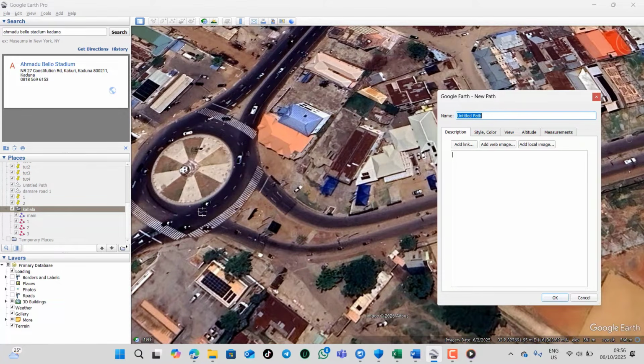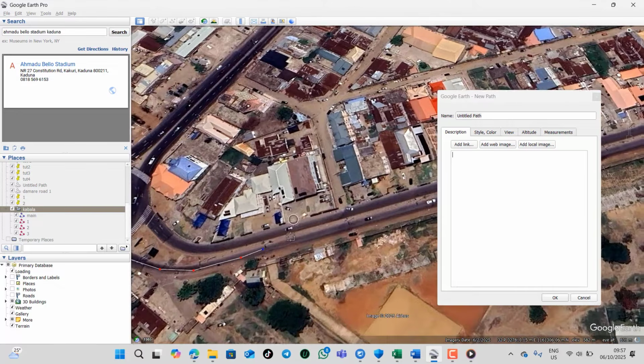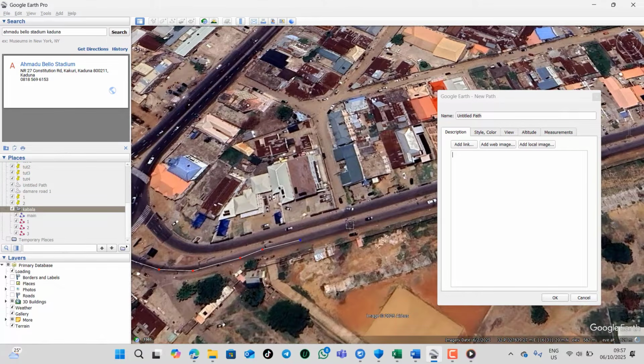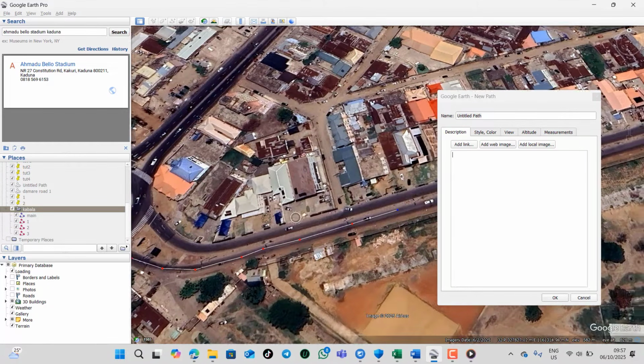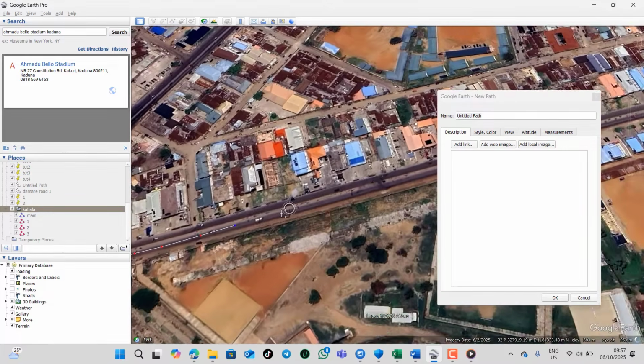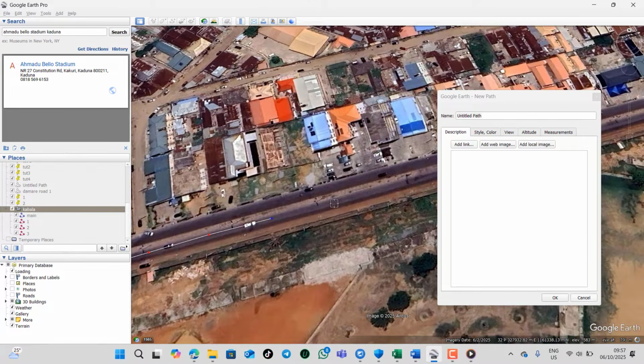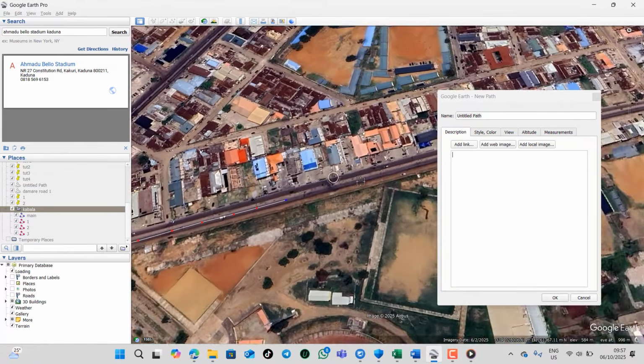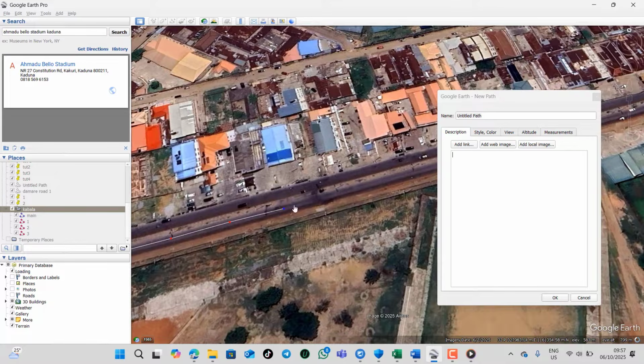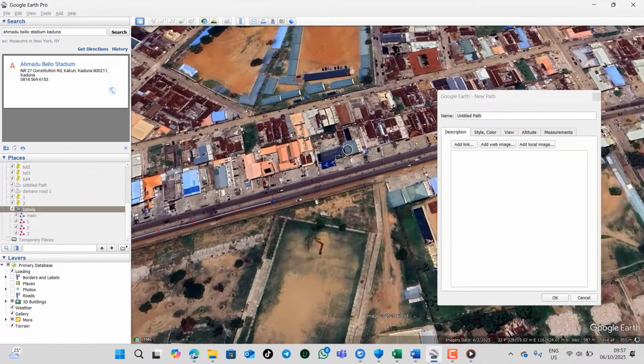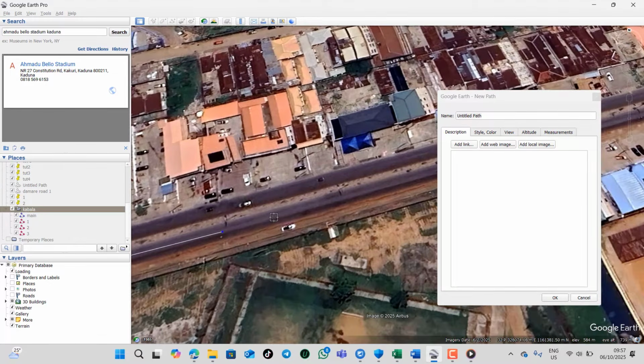So I am just going to take this point. You can do it at a regular interval, like I said, but this is not very recommended for a real life project. You can use it just for a proposal. By the time you are mobilized to do the job in real life, you have to go physically and take these points. It's important that you go to the site with a surveyor and take these points.